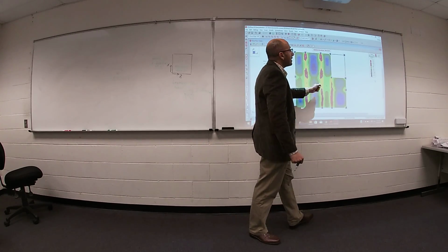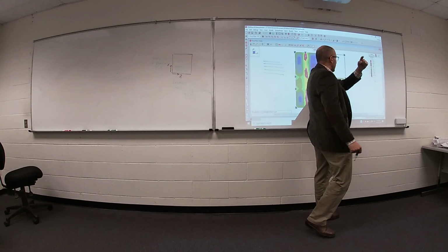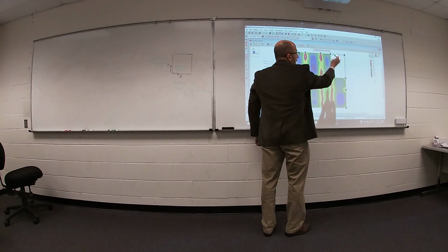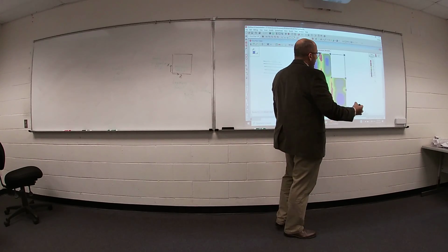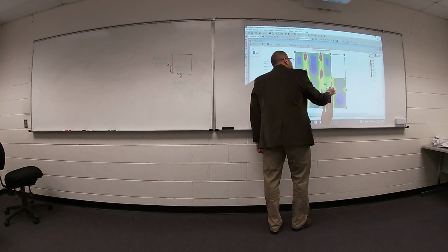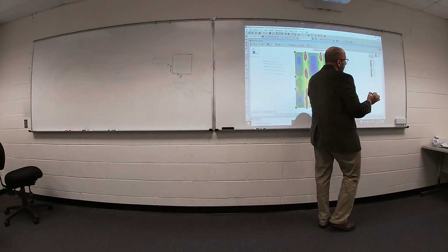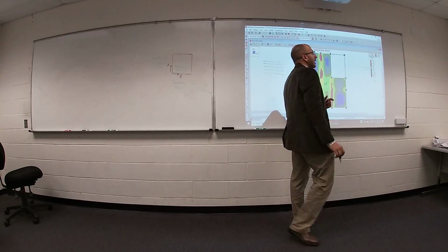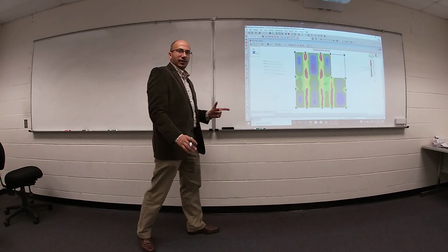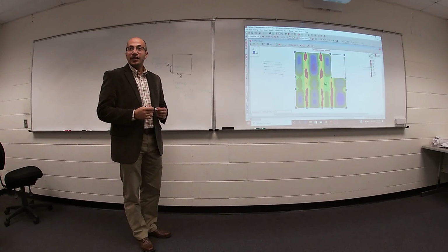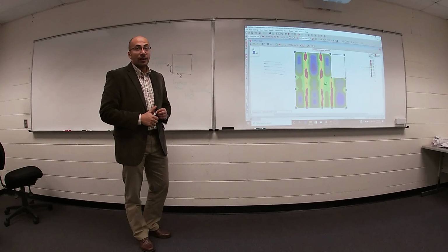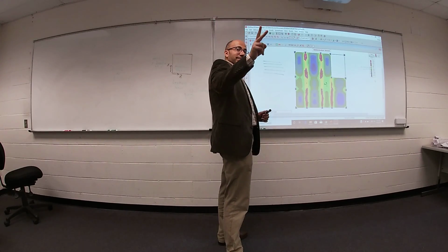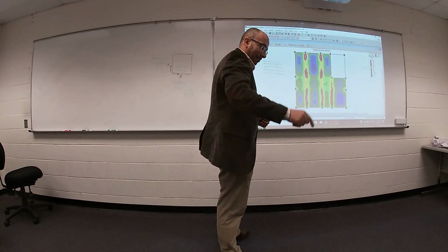If you would like to read the meaning of this color, go ahead. Any color has a range of bending moment. For example, any point that has green color, that means any point inside this area will have a moment between 0.05 to 0.47 kip-feet. So if we look at it, that means it's bending up. What do you mean? Like going up.